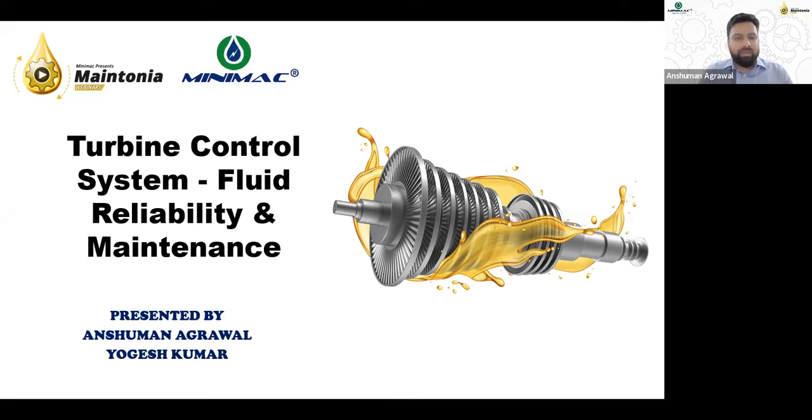So all these three names: one is control system fluid, a name based on its application. The second is fire resistant fluid, a name based on its property of fire resistance, and phosphate ester fluid or polyol ester fluid based on the chemistry of this fluid. These three names are all talking about the same entity, that is the fluid which is used for the purpose of turbine control systems.